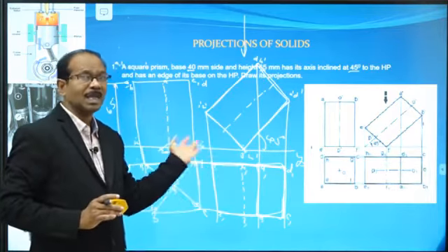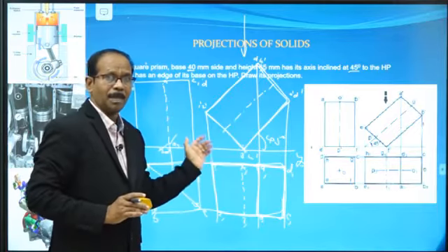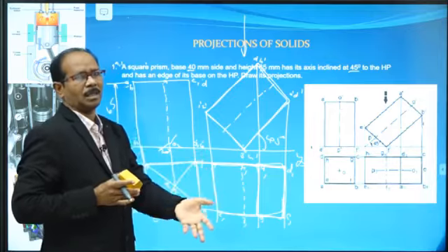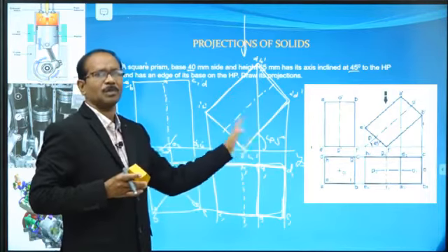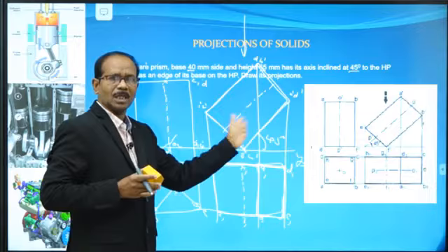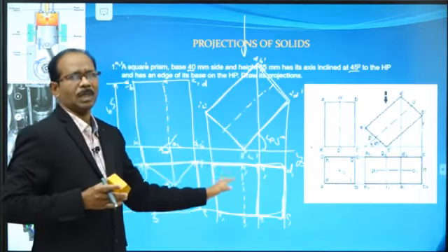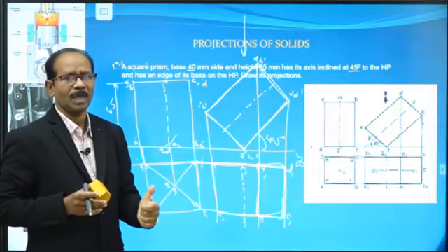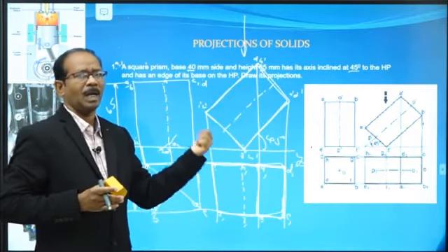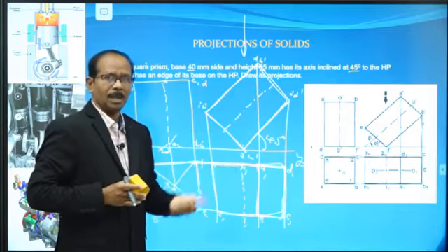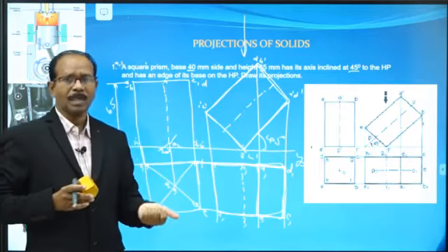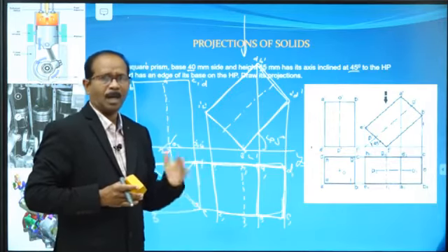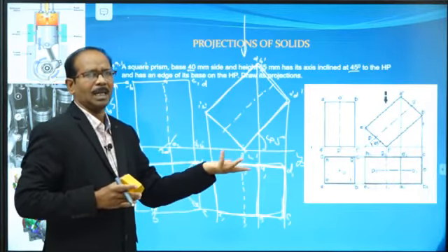Which one is the result, which one is the construction. All lines should be there, but some lines are used to construct the final object. You constructed using all these procedures. The final object is this one. Highlight the final object only. So this is about a square prism of side 40 mm and axis 65 mm at an angle of 45 degrees. Based upon this concept, for any diagram only the shape of the base, the height and the angle change.